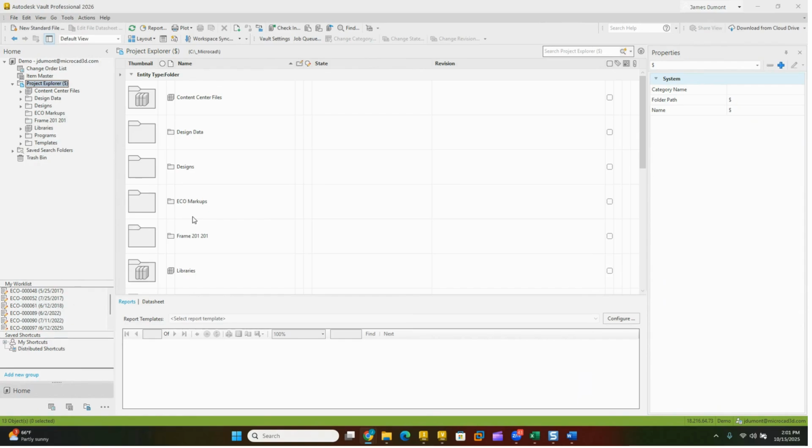Yeah, so there is a potential for having to rename a ton of file names upon check-in when using one vault and a force unique file name setting. Huge inconvenience. It can be. If you're creating files with similar names, if you're using Vault Basic, you have to have a naming strategy. If you're using Vault Professional, you can use the automatic numbering, which creates unique file names for you, and it makes things a lot easier.